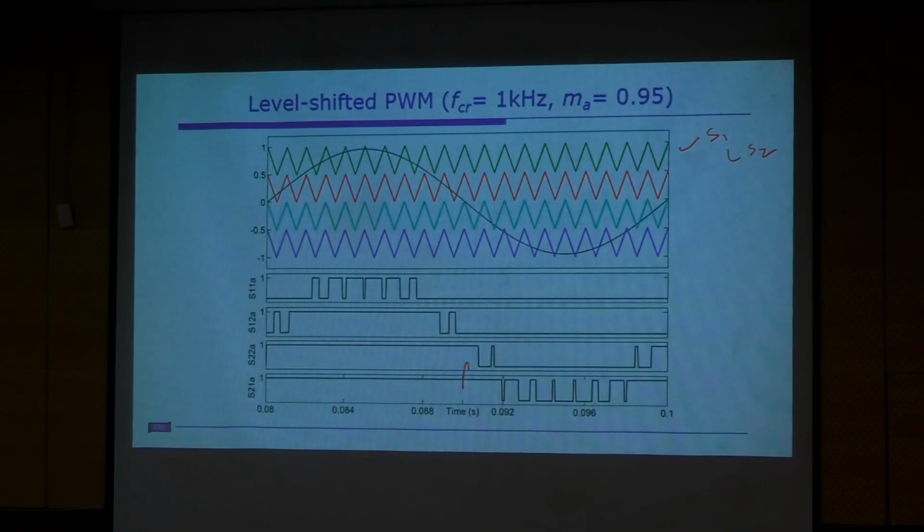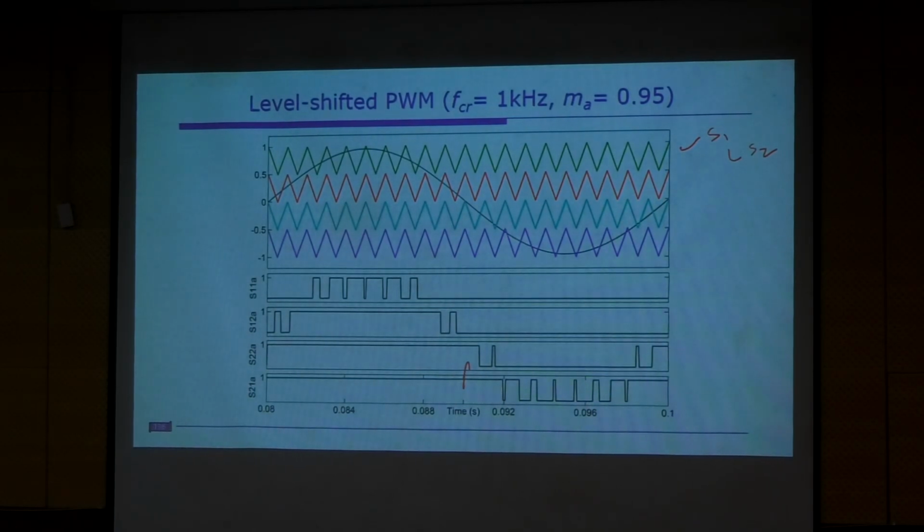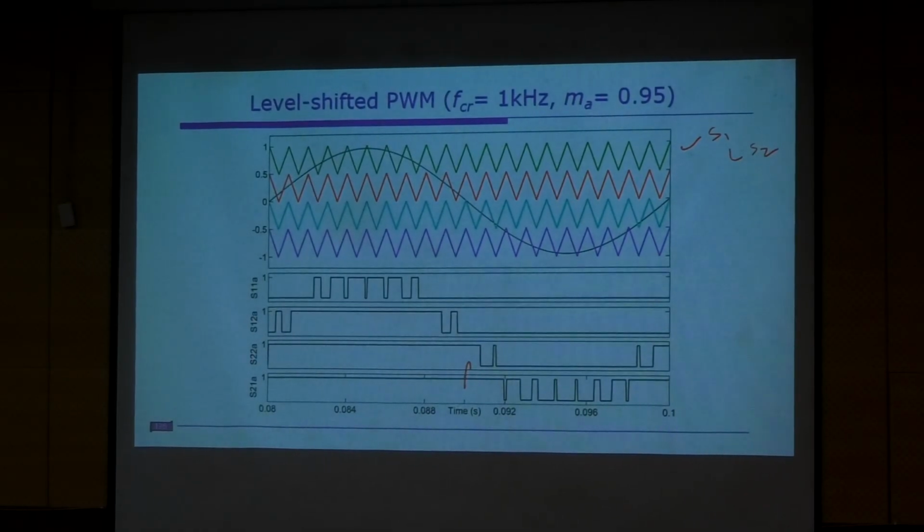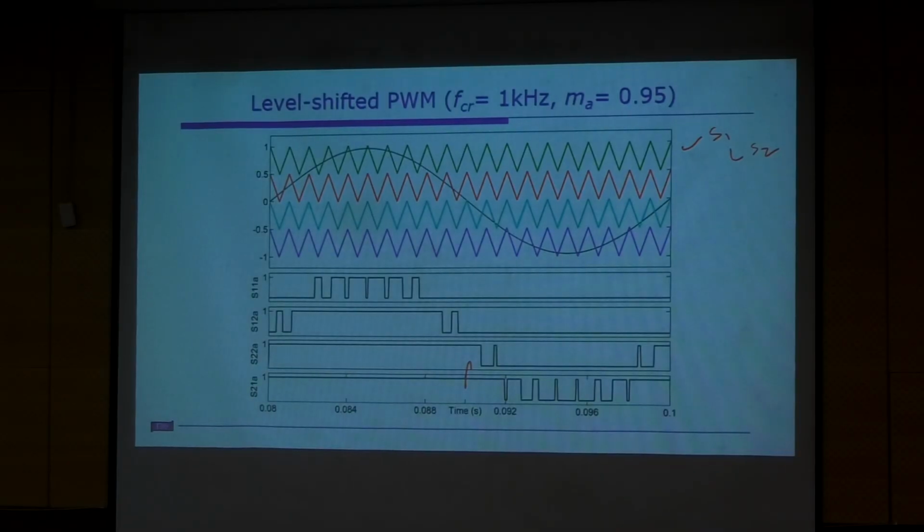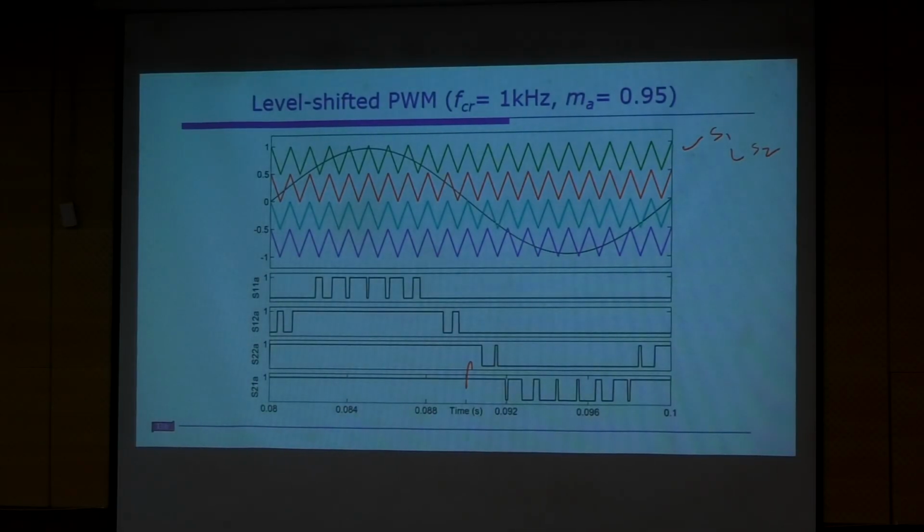So normally, when to take ramp and when to take triangle, there are two things: the single edged and the double edged signals, right? The ramp signal is usually for DC. Whenever you want to reduce the ripples in the output voltage, generally the ramp signal is preferred. That is the single edged one. If you want to reduce the harmonics, you need to use the double edged one, like the triangle carrier. So if the output voltage you are supposed to control is DC, the ramp waveform is preferred. In case of AC, you are supposed to use the triangle carrier. That is the basic thing.